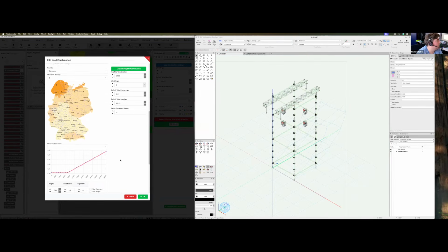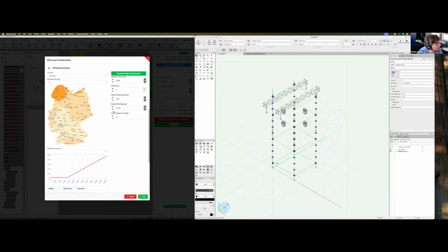An important thing to know is that we also put in a temporary usage factor. These kinds of wind loads that you put in there are calculated on a 50-year basis. So, simplified, they check what's the highest wind speed in this region that they saw in the last 50 years, and that's the value that you assign for calculation.